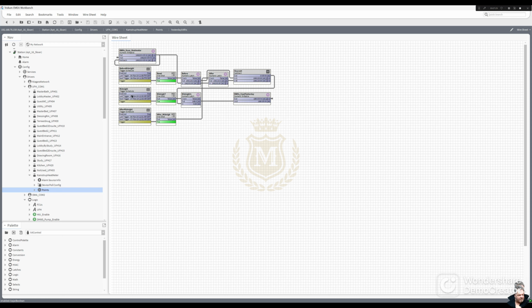I then take a snapshot of that value to put it into there. I've got a history attached to that, and then I will reset it. So again, I'll have another 24 hours before we go to the next snapshot. So it's simple enough logic, but it works quite well. So it's taken the current heat meter kilowatt hours into there, and then that's the after one, which is fired by this one here.